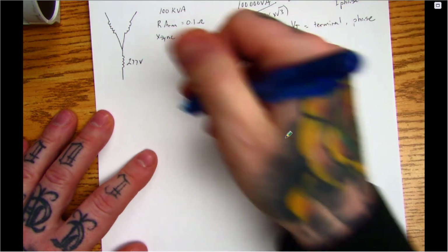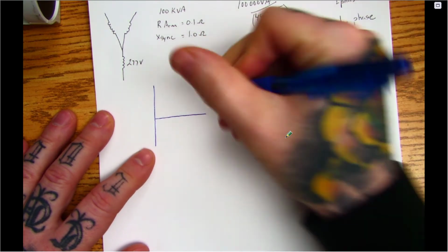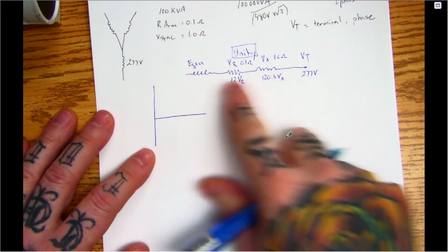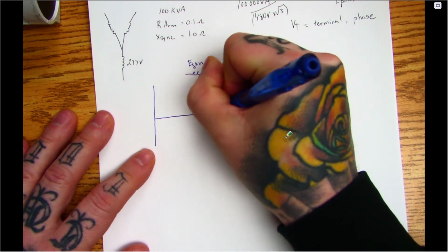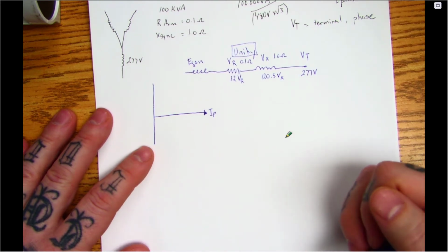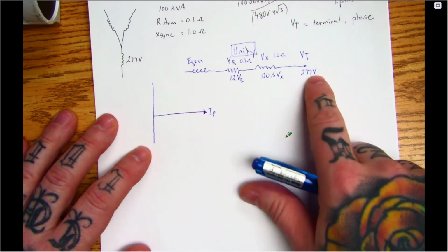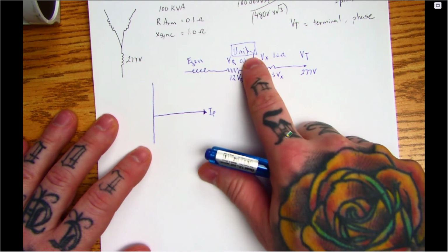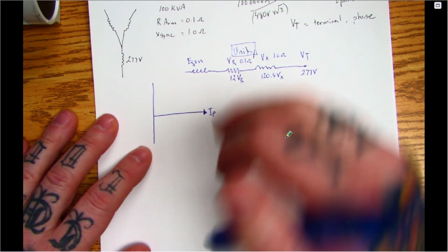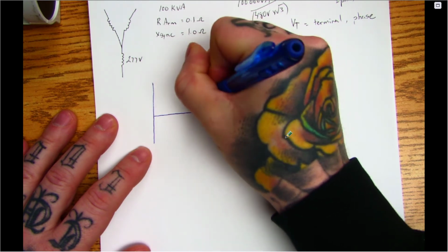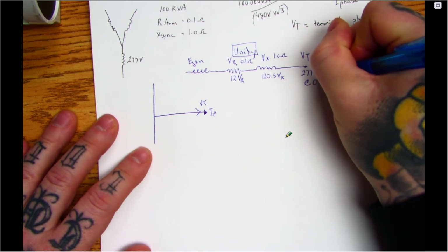So I'm going to first reference this to a phasor diagram, where again this is a series connection where we have different volt drops. Current would be my reference here, so my I phase in that case. And then I'm going to plot these voltages against this current. The 277 is a terminal voltage. If I'm at unity, I know that this phase voltage is in phase with the current. So my 277, or my VT, is going to go right there. So I know it's at 0 degrees.